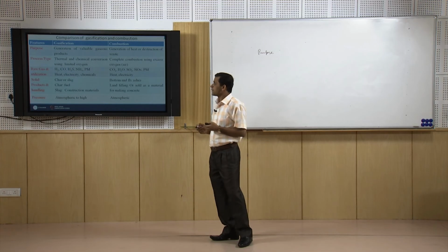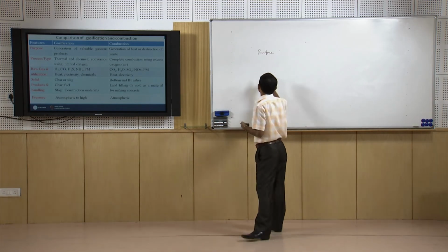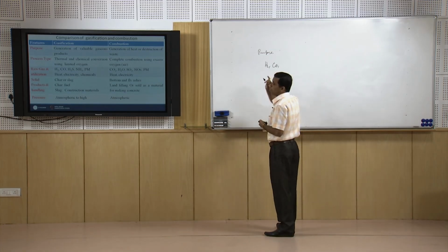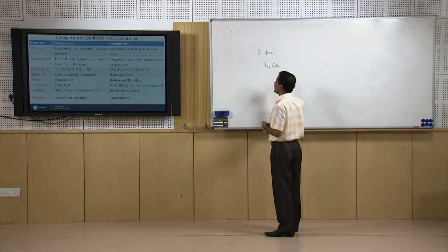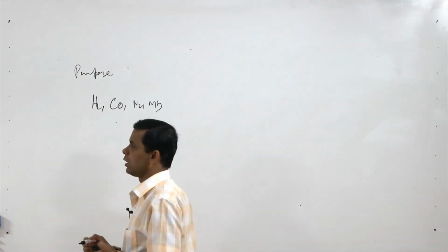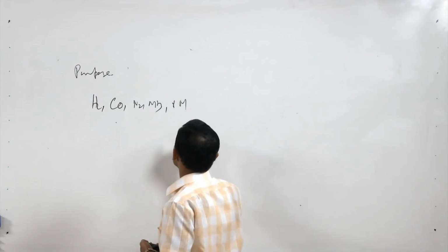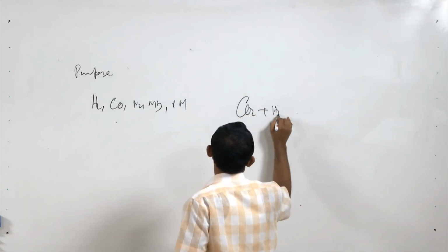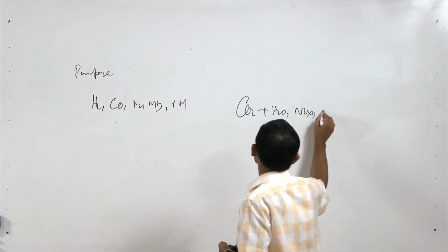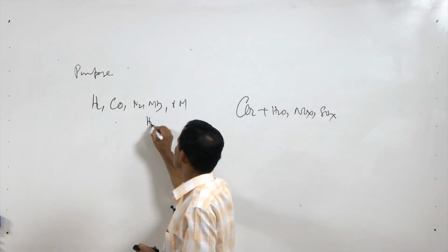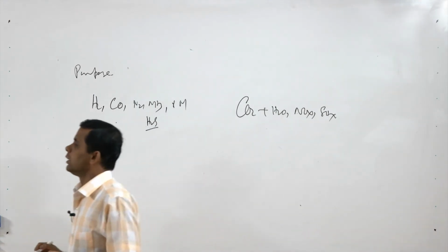And raw gas: the gasification contains H2, CO and no NOx, it contains nitrogen or NH3 if air is used, or PM, but in case of combustion we will have mainly CO2 plus H2O, we will get NOx, we will get SOx if sulfur is present, and in gasification, if sulfur is present, we will get H2S.